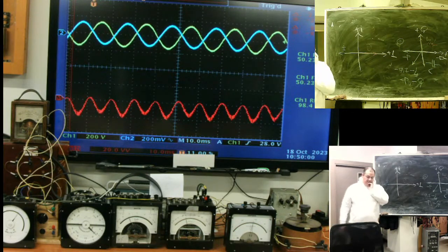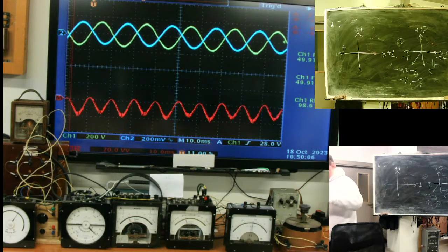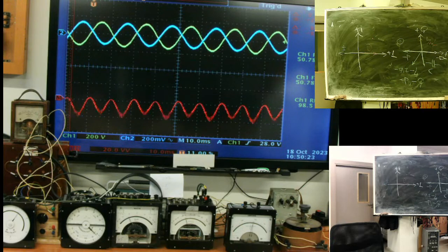If the machine is alone, we will see just an increase of voltage. But when the machine works in parallel with the network, it can change voltage of the whole network. And it means what? The real EMF of the machine starts leading.